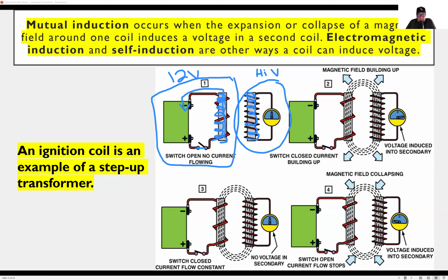That side is not connected to the battery. So it has to go somewhere because we just removed its source of power, its source of magnetism. Now, in order for this to work, what this magnetism and electricity is going to do, it's going to go into the spark plug. It has to find a ground. It has to get out of here. It has to get out of the coil. So it's going to go through the spark plug.